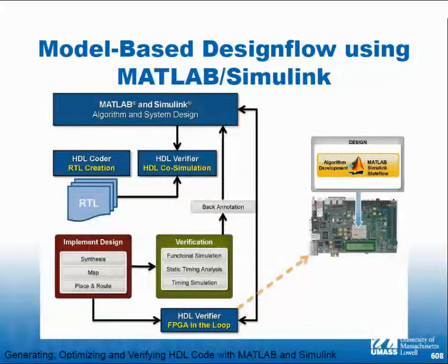model-based design flow. Now, remember, I hope I said this on the first night, that I wanted you to stop thinking about putting code into a simulator and running a test bench. I wanted you to start thinking that everything was a model and the simulator was just something that calculated those models. So the simulator is full of models of logic gates for your DUT. The stimulus generator is a model. The response checker is a model. And the simulator is a calculator. And you dump all this stuff in and say go, and it just calculates until you program it to stop or you hit stop. So that works well here.